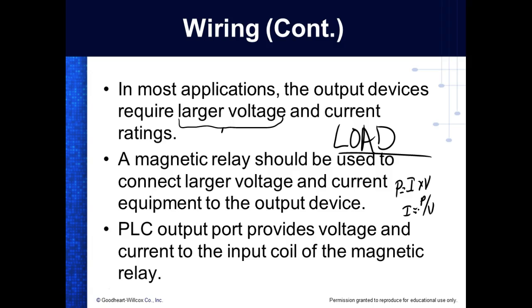Now, the higher the voltage that device is rated at, the less current's required to provide that what? Power. Which means what? We don't get more power out of 1,000 volts, and we could get the same amount of power out of 100 if it's rated for it. Out of 100 volts, we could get the same amount of power out of 5 volts. Look at your car battery out there, right? Most of them are rated like 200 amps at 12 volts. That's 1,200 watts of power that the car battery can put out.